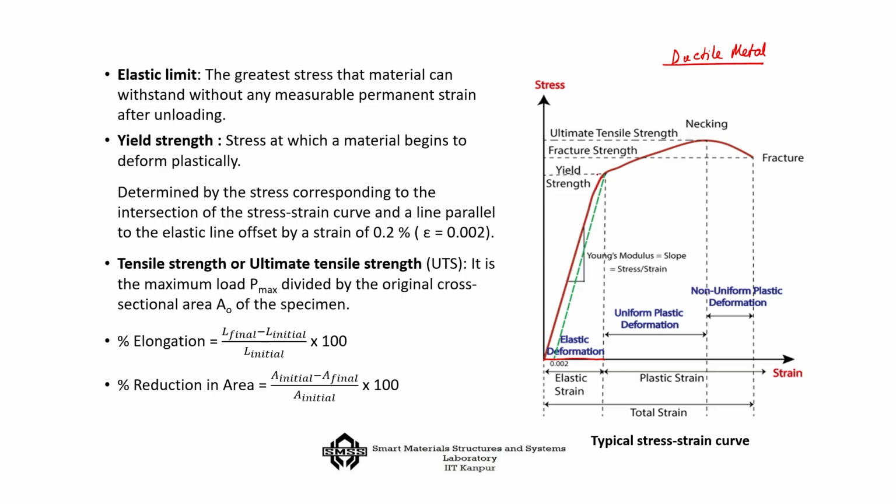Okay. So, the yield strength is defined with respect to this region itself, and however, this region has some part, you can see that up till this point there is linearity, and then this little bit of it that is nonlinear. Okay. So, this part is nonlinear, and yield strength is defined in a way that if you remain below this region, then whenever you are unloading, you are going to come back to 0. Whereas, if you cross the yield strength level, then actually the plastic strain starts to accumulate.